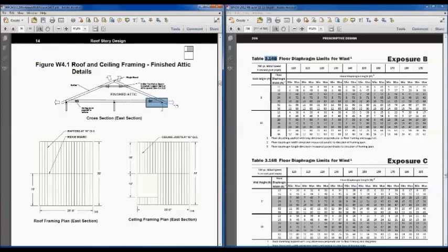So in this particular case, we've got floor joists in our attic that span across the entire system. There's a load-bearing wall here in the middle, so we're going to have 16-foot floor joists in that attic system across that 32-foot roof span. So for our rafters at 16 inches on center, I'm sorry, these are the rafters. I should clarify that. These are 16-foot rafters. This is the ridge across that 32-foot roof span.